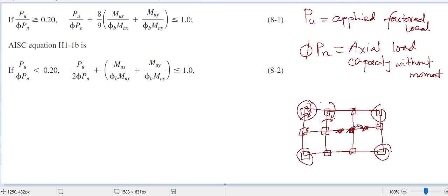Sometimes we assume this side is loaded and this side is unloaded, which means there will be moment here also. We do this to consider the unloaded case, because if a building is big, there is a good chance that one floor or one room will be loaded and another room unloaded. It is possible. So there are different cases where moment may come, but the final statement is that most columns in this world have moment, whether reinforced concrete column or steel column.